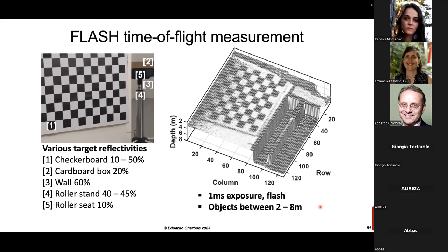So one wants to use an excess bias voltage that is as high as possible, because the higher the excess bias voltage, the lower the sensitivity to breakdown voltage. So in other words, a very small variation of breakdown voltage will result in less and less variation at the pixel level of PDP. So there's always an interest in increasing the VE, the excess bias voltage, as much as possible.